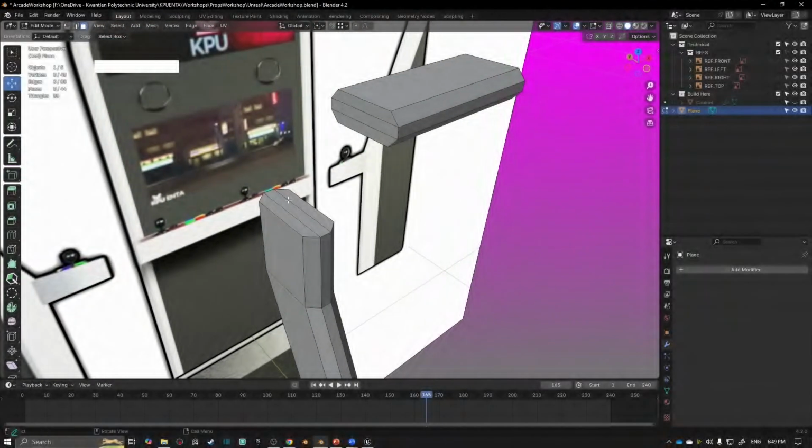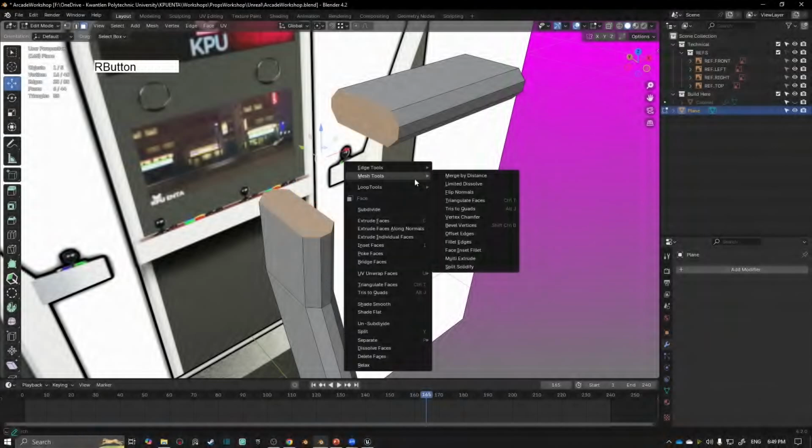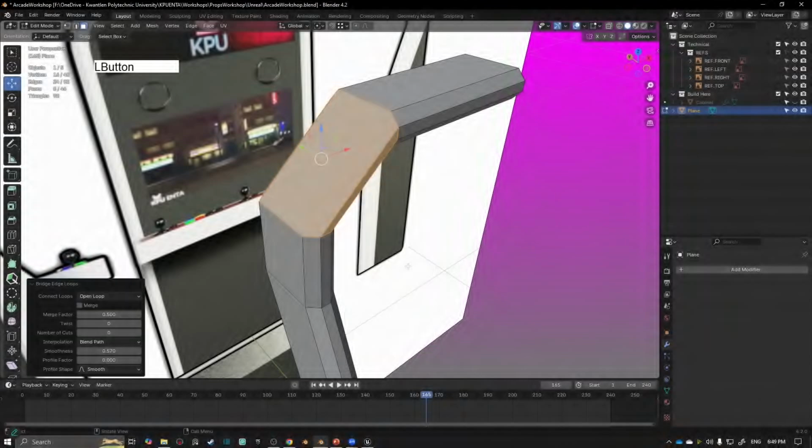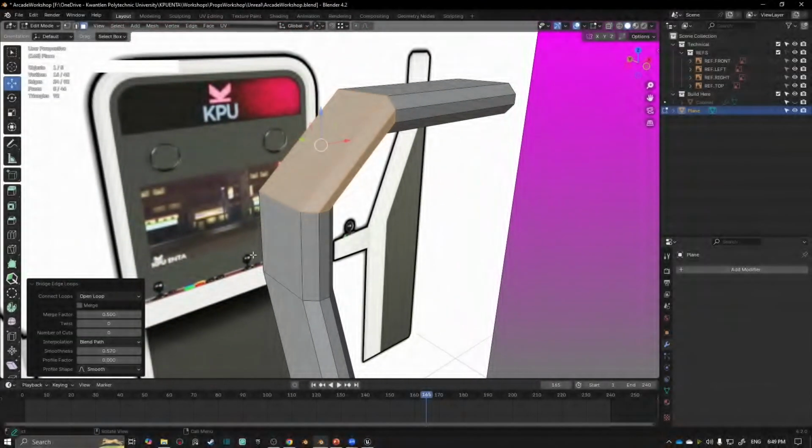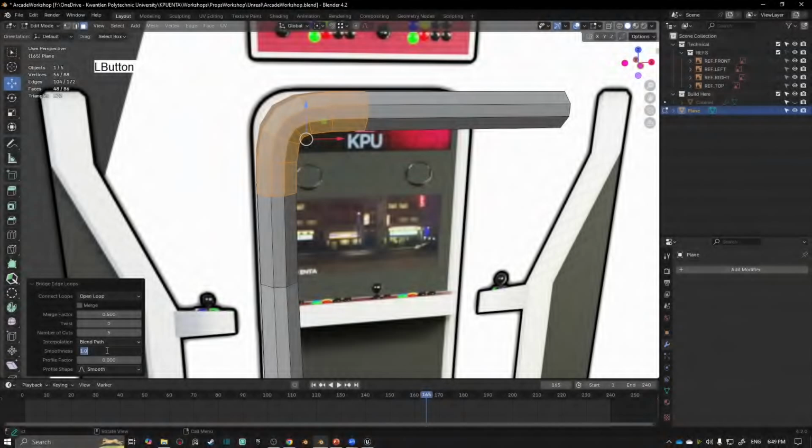Okay, so we've got a surface here and a surface here. I'll right click, bridge my faces. I'm going to increase the number of cuts. Now I'm going to use 5 because I used 5 in the other space, so it'll just be easier to blend. Where this was 1, I'm going to reduce it down. I think 0.57 kind of worked for my particular profile there.